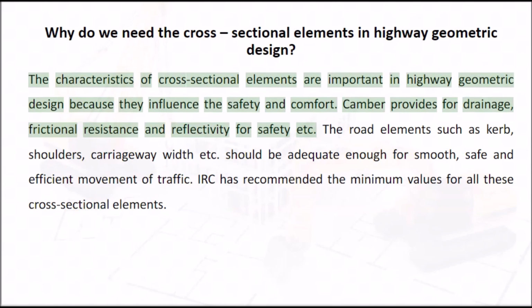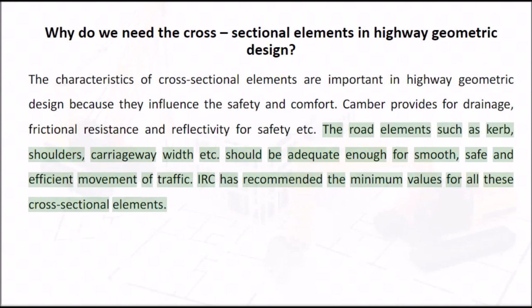Camber provides for drainage, frictional resistance, and reflectivity for safety etc. The road elements such as curb, shoulders, carriageway width etc. should be adequate enough for smooth, safe, and efficient movement of traffic. IRC has recommended the minimum values for all these cross-sectional elements.